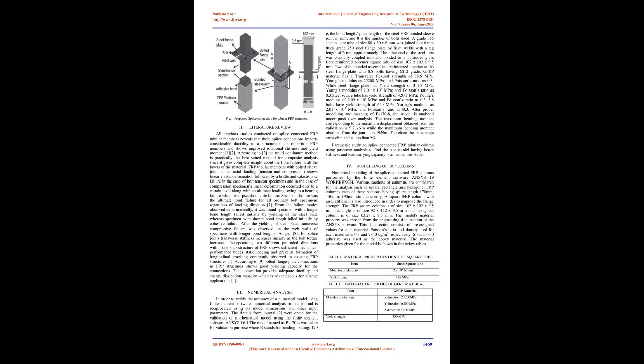[1] Adhesive bonding, as an alternative, offers structural integrity, reduced stress concentration and also improved fatigue resistance. Combining these benefits of the adhesive bond and the steel sleeve connector, bonded sleeve connections for joining circular GFRP truss members to nodal joints was proposed.